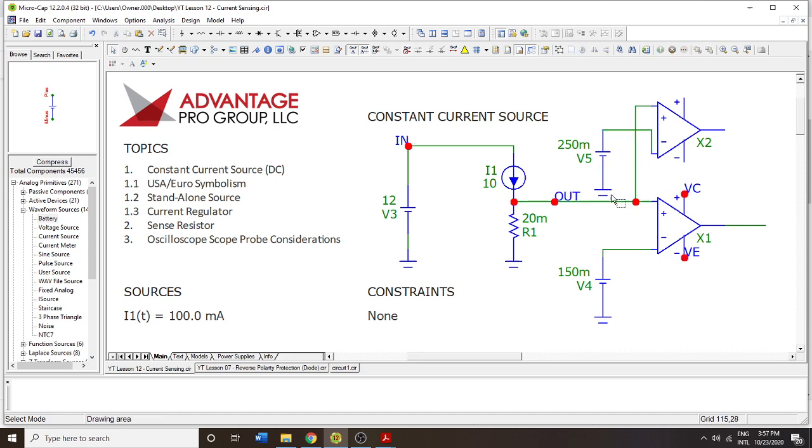Okay, so then now this is your level 2 error. So if the current passes through the level 1, you just get a warning, and you say, okay, slow things down. But if you go into the second circuit and your voltage starts to exceed whatever this reference voltage is, then it's like, okay, now you've got a real problem. And you could take the difference in time, and so you could take the rate between these particular moments, and then you could get a trend. And then you could know, oh shoot, we're headed towards disaster. The current's going out of control. So this is one way that you would measure and make decisions off of it.